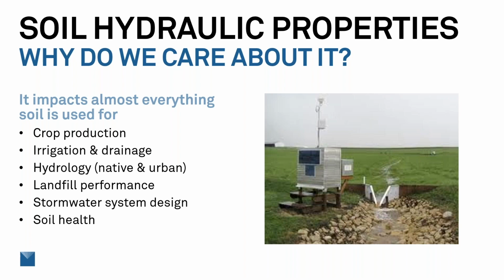It also has an impact on the hydrology of both native and urban environments. And it's also used in landfill performance, trying to estimate the efficacy of landfill covers, whether it's a cover designed to limit the water movement through soil, or a cover designed to store water, those evaporation type covers. It also impacts stormwater system design, both measuring the native soil properties and, if you're engineering the soils, what the soil hydraulic properties of the engineered soils are. And one topic that has been much more popular recently is soil health, and what role these properties play in determining if our soils are healthy.